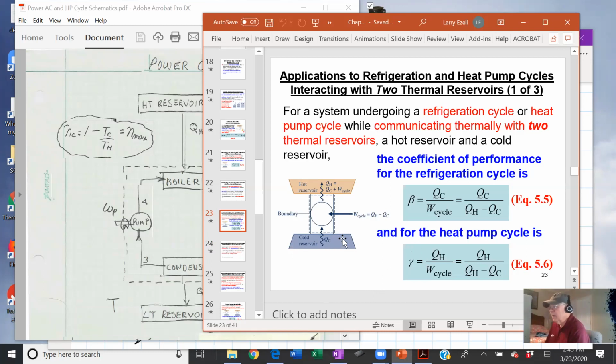But here's the difference. In a heat pump, the work you put into the compressor actually goes into the heat in the fluid and comes out in the area you're trying to heat. In other words, you're able to use the energy you put in to run the compressor as part of the energy to heat. That's really neat. The problem is practical, in that if it gets cold enough outside, you can no longer pull heat.